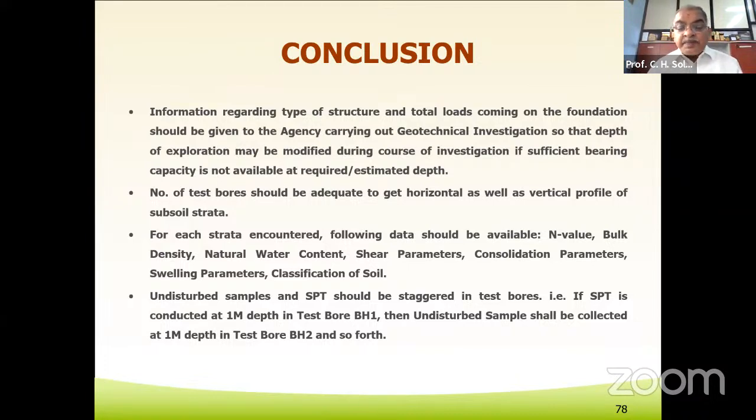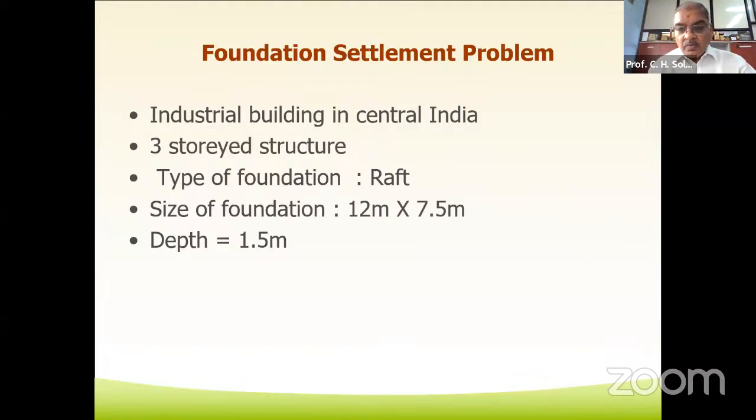Undisturbed samples and SPTs should be staggered in test bores. If an SPT is conducted at 1 meter depth in borehole number 1, it has to be conducted at 2 meter depth in borehole 2. Likewise, the staggered performance of the SPT at the intermediate depths has to be done.